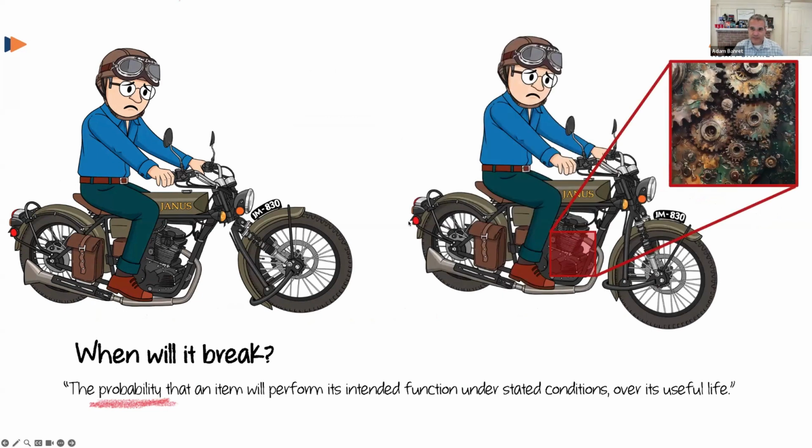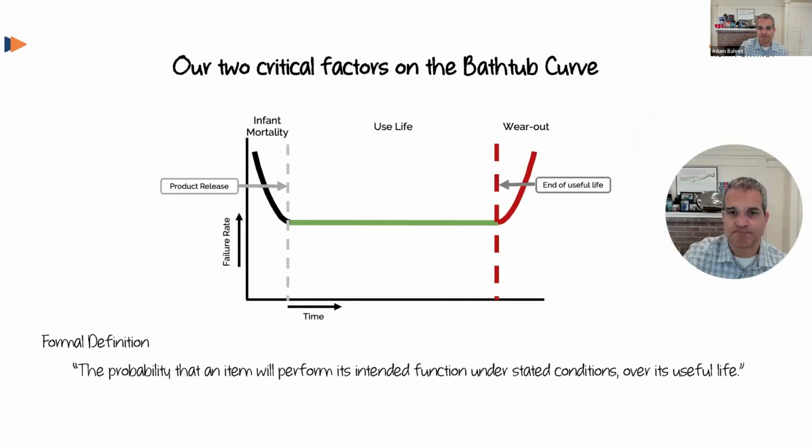So what about the second one? Useful life is about when will it wear out. And these are predictable. And these failure modes, to some degree, for any product that lasts long enough, they will experience them because it has to do with actual degradation from the expected stresses. So it's really important to differentiate between these two types of failures. And especially when we're doing something as specific as auxiliary life testing, you have to make sure that you're always keeping these two separate.